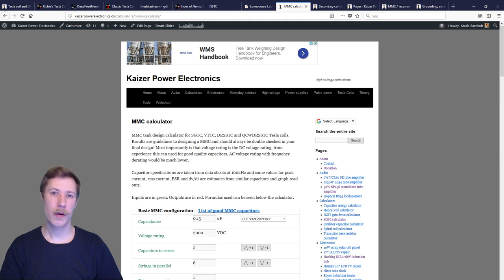It's an interesting point, because if you made a smaller Tesla coil, of course you can use it. A lot of these thermal issues are first an issue when we get above a certain limit of primary peak current. So are you operating at some sub 500 ampere? That's, well, yeah, don't we just call that leak current? Or yeah, fault currents. Everything below 500 ampere is fault currents.